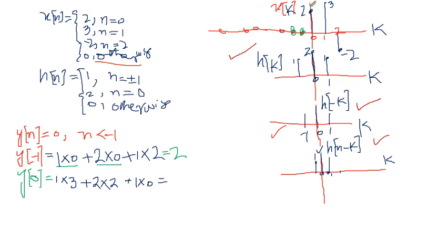Maybe we can use a word, SMS, to show how the convolution sum is done. The first S means shift, then M for multiply, and then S for sum. So this basically follows S M S. Then again shift, multiply, sum. So we shift, then we multiply.